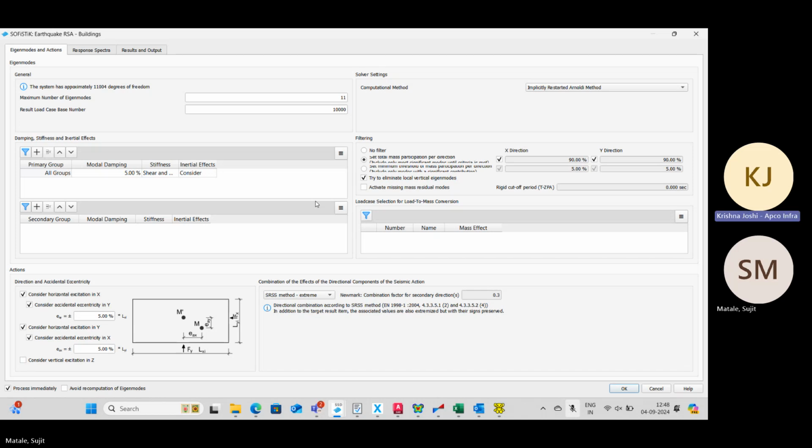That means what is nonlinear stiffness, and gradually you go here, but it goes iteratively. So it gives updated stiffness in each iteration that you get. Asking for a member, right? Member stiffness wise, generated. It's not that it cannot be generated. This was asked to be generated and then you have to re-feed it into the system.